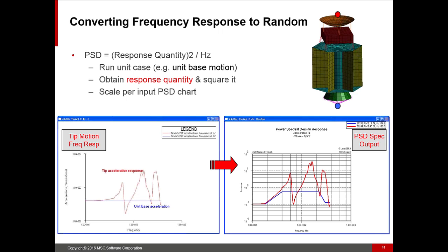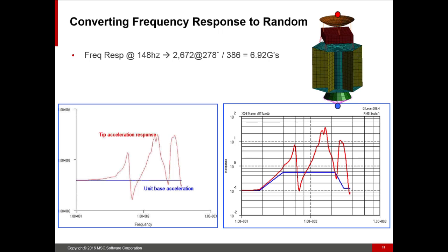So if we look from plot to plot, all that we've done, usually the input is much higher at a certain frequency range. I'm not going to get too much into that. You can see the input PSD goes up and then at higher frequencies, it drops back off again. So that's just a product of usually the way most of the structures work. And of course, that offsets what the loading is that we will see up at the satellite dish, at the antenna part of it.